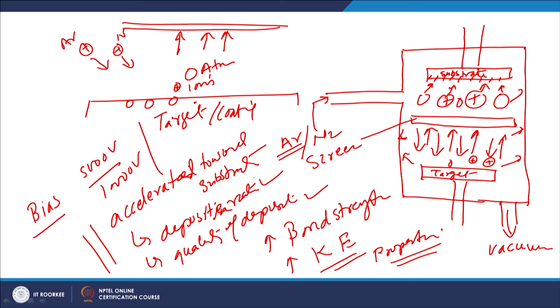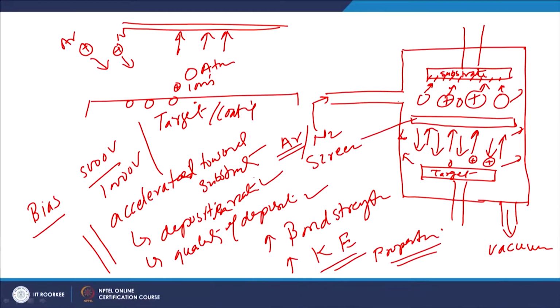So, this is the general principle of the sputtering process. We use the high energy ions which are directed onto the target material, and this target material will be producing the atoms as well as ions. These will be coming out at a higher speed from the target material, and then these will be moving here and there. Some of these will be moving and impacting with the internal surfaces of the chamber, as well as some of these atoms and ions will be depositing with the substrate.